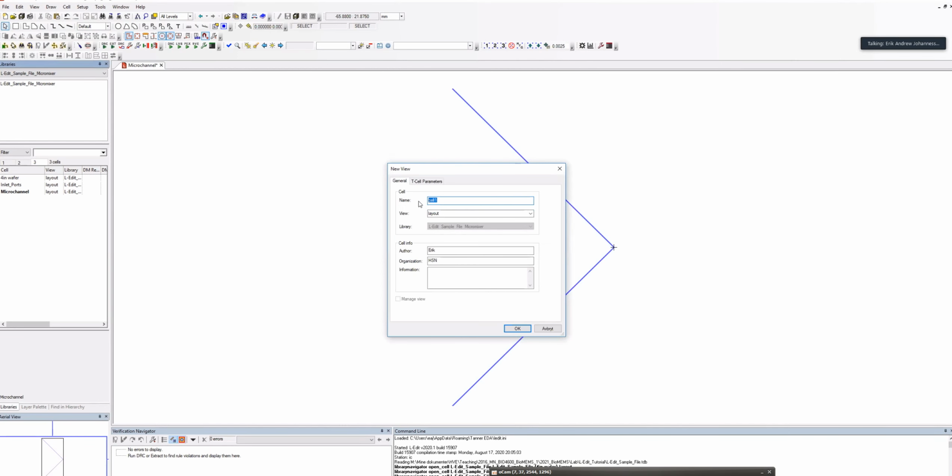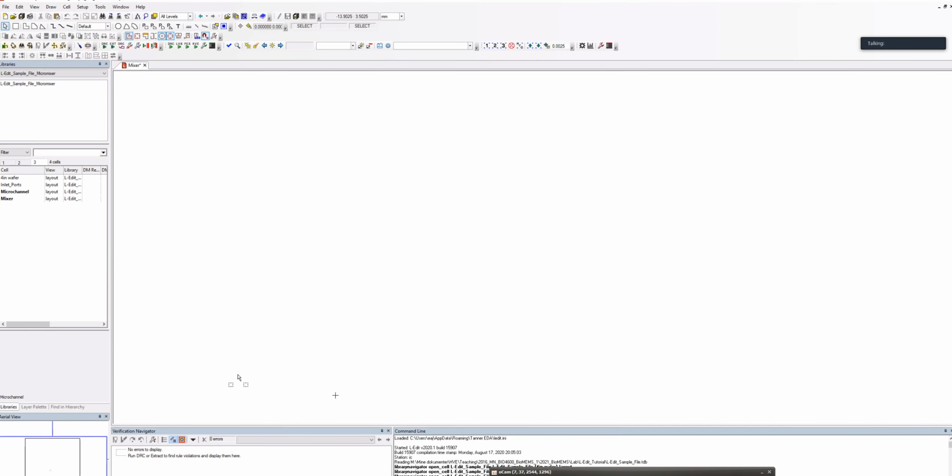And we call this mixer, like this. And here you're going to design the mixing channel in the same manner as I just showed you. Of course, the dimensions will be different from the inlet channels, but you're following the same methodology as just shown.